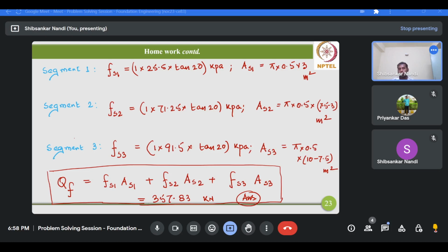With respect to that eccentric inclined loading, we have determined the factor of safety against bearing, though we can also determine the factor of safety against sliding. In addition, we have learned a little about the permissible limit of eccentricity which you can allow in practical field conditions.